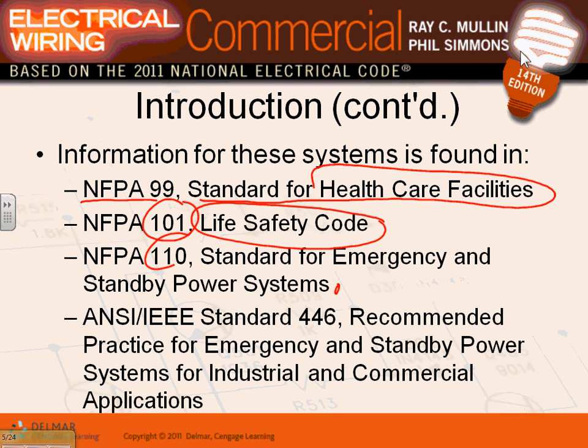If that's not enough for you, there's ANSI and IEEE. Recommended practice for emergency and standby systems in industrial and commercial buildings. It goes into how to test them. It's not enough to put a generator sitting there. When you call on that generator to come up, it's not going to come up because the battery is dead. So they have procedures for how to test this equipment.